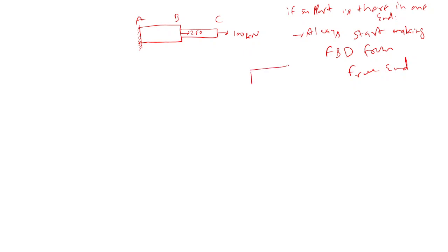Let's suppose, for example, I'm not going to solve this, I just give it for practice. Because at the free end 100 is there, to make equilibrium 100 would be here, right? So 100 here. Now the net force would be 250 here, but 100 already came here. So at that junction you have to put 350 this way, because 350 and 100 give 250 net here. Now to keep equilibrium, 350 would be here. Correct? Yes, sir. So this way you have to do.